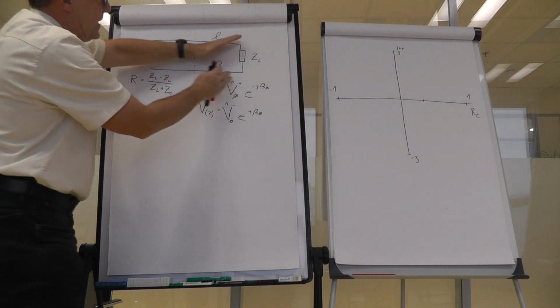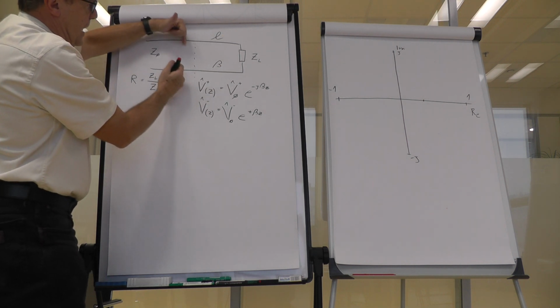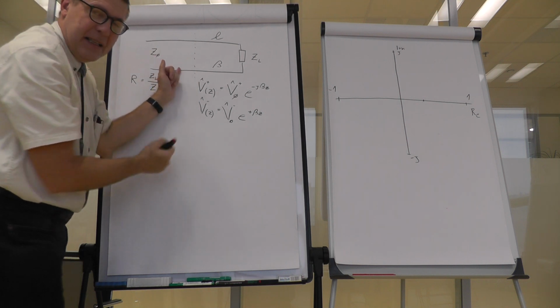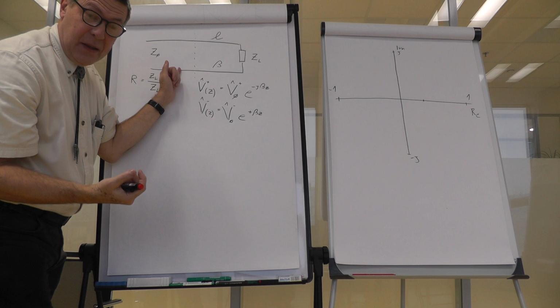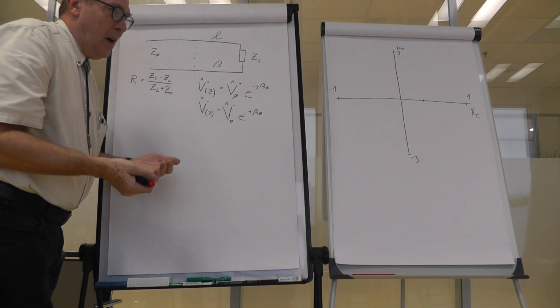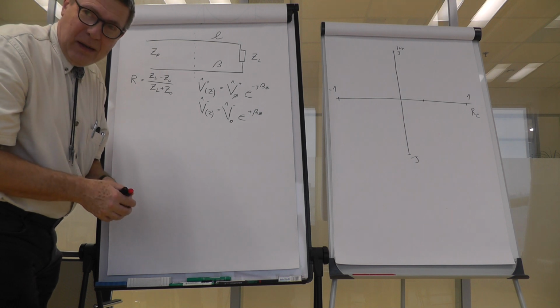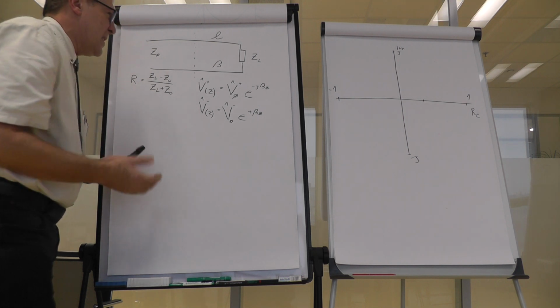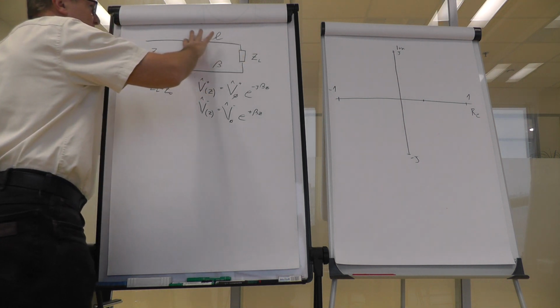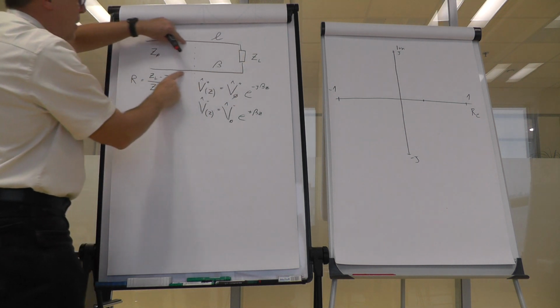So the line is intact, just the voltmeter is capable of measuring voltage, and at the same time it cuts the line and is capable of measuring current. Or let's say it uses some kind of clamp current meter which does not destroy the line. So we can measure voltage and current, and we would just slide along the line.